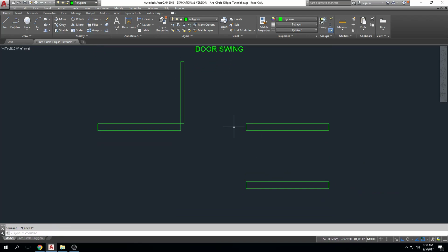So I'm going to move this down a little bit, and we are just going to talk about the from command. The from command will allow me to draw geometry a specific distance from a first piece of geometry, right? So when I'm using it, I'm creating a gap of some sort. Okay. So I initiate whatever command I want to use the from command with, click.